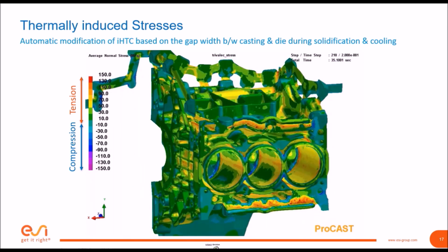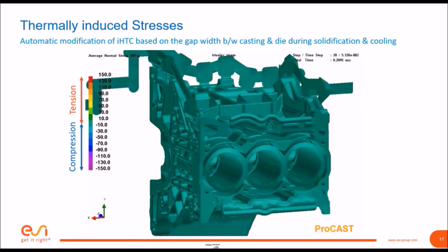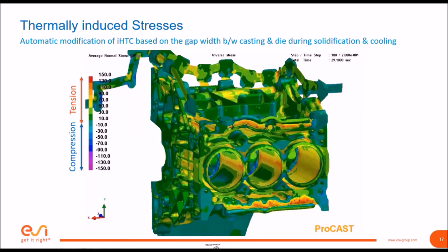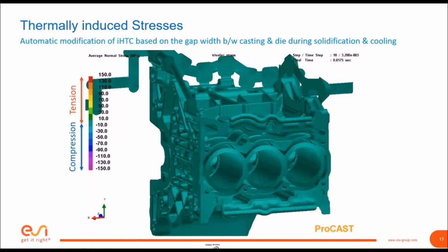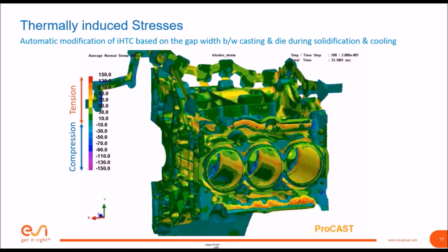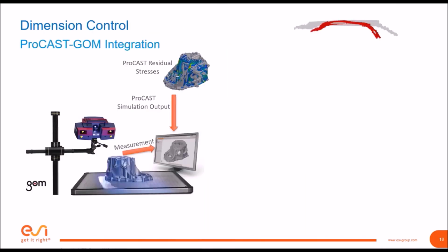And there are several aspects from, let's say, the residual stresses. One is able to predict the hot tears or cracks. And one main important thing is that, because all these parts are very thin-walled parts, they are going and fitting into another sub-assembly or assembly. So it is the dimension control. One is required to achieve this dimension control, and it can be achieved in several ways.